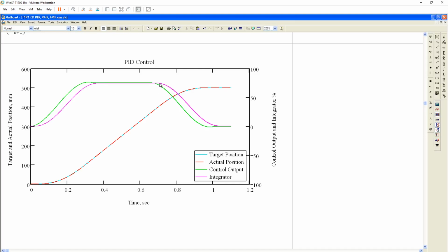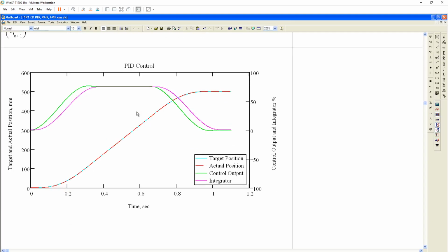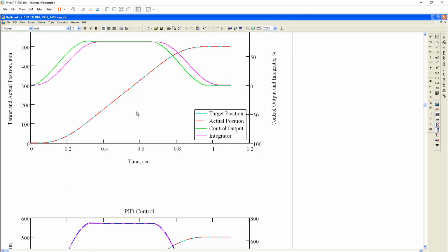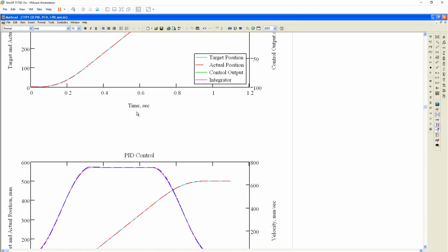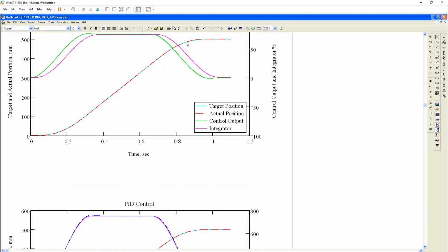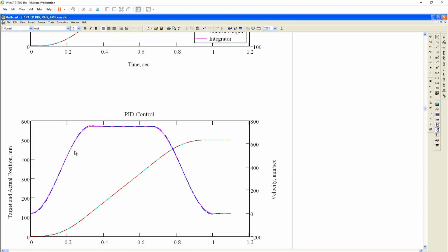This is another third of a second. You add the two together, get 2/3 of a second, invert that, and you get the frequency of acceleration, which is 1.5 hertz. But the controller and the system have a bandwidth that's greater than 1.5 by a large margin. So it tracks fairly well, even though there's no feed forwards. There's a little bit of error in here, and you can see the error show up a little bit more when I'm plotting the velocities.